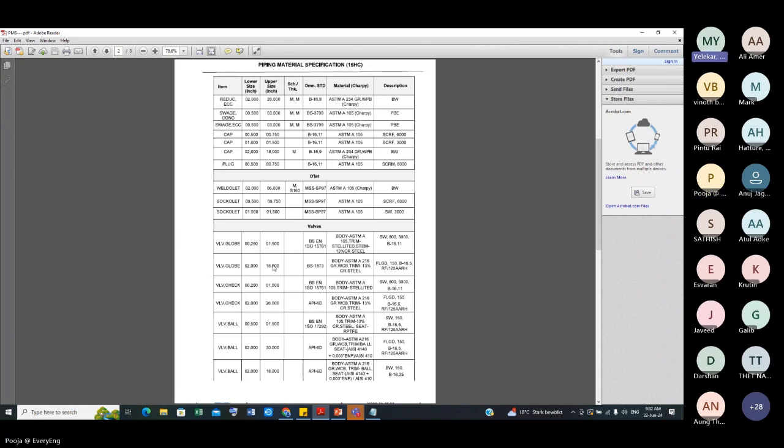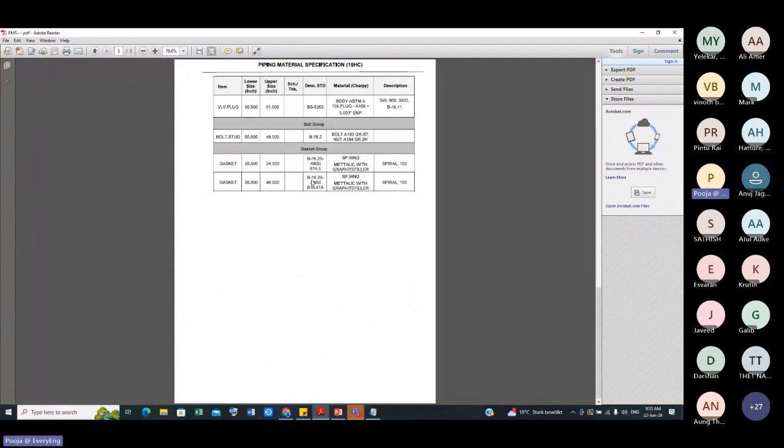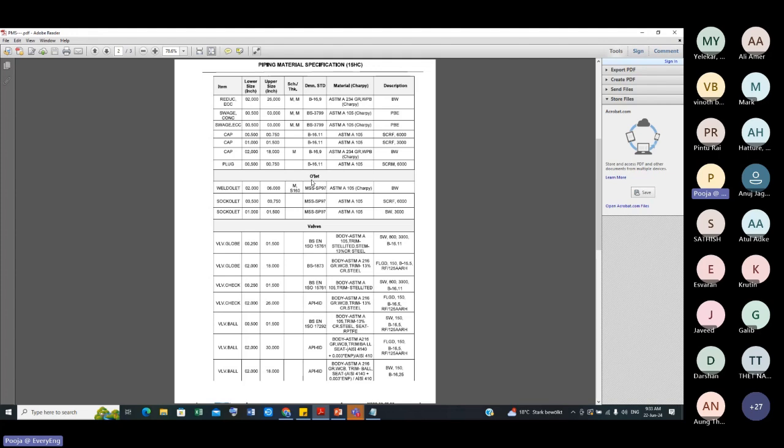Yes, we can. Yeah. So as I said, for the bigger sizes, meaning 2 inch and above, we use casting material for the flanges, body, then trim. But is only this information sufficient to order a complicated component like a valve? Definitely not. At the same time, we cannot specify all this detail in this document. Otherwise, for the globe valve you will specify this much data, again for the gate valve this much data, and your document will be a very huge document.